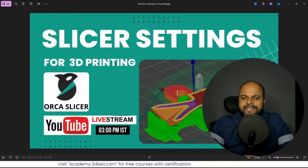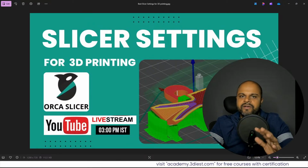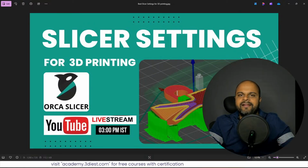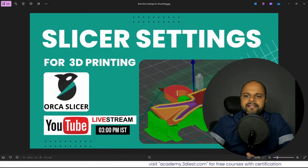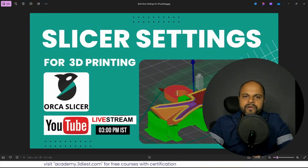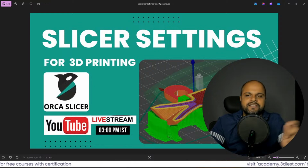If you have studied engineering, there is a subject where for CNC machines we used to write G codes, right? By using those G codes, our tool will move. In a similar manner, it works on the same principle in the case of a 3D printer. And the slicer automatically creates the best suitable G codes based on the settings you provide, the preferences you give, and the materials you select. That G code you can then upload to your 3D printer, and then it will start printing. So basically it's a middleman that helps you convert your 3D model into the language of your 3D printer, right? So this is what we're going to learn today.